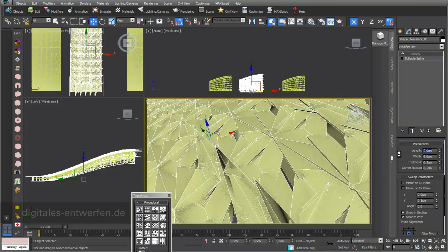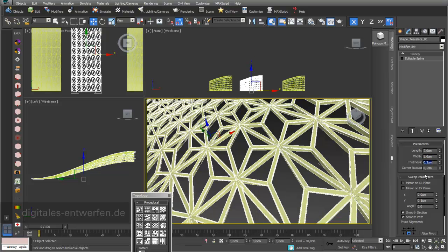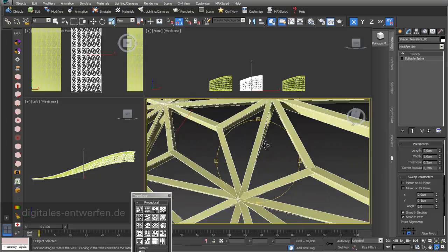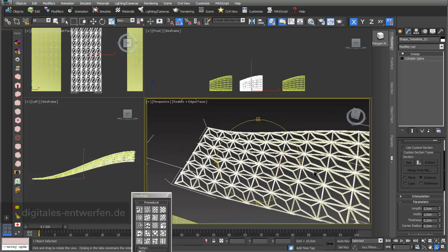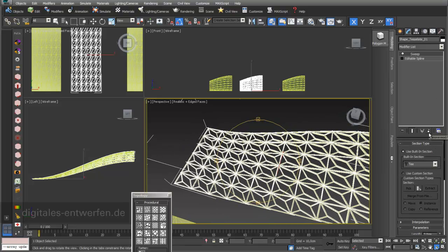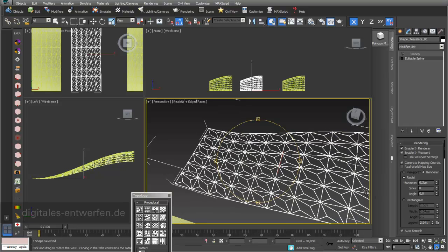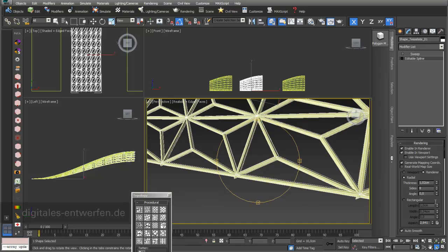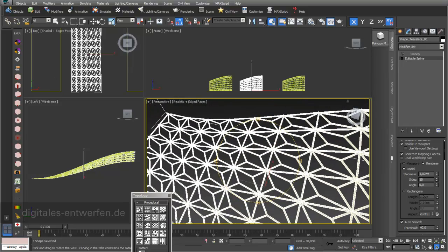This definitely looks a little bit weird right now, because my T profile is definitely too big for my shape, but if I adjust it a little bit, then you can already see that this actually looks quite good for the beginning. These are just T profiles, and you can do a lot of things with this. Sometimes the basic settings, like in my editable spline, radial or something like this, always work properly, and then sometimes there are issues with the corners, and we will come back to this later on. Okay, so the first method is based on my edit poly edge object hierarchy.